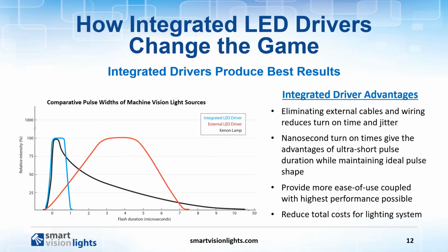Integrating the driver and controller in close physical proximity to each other on an LED motherboard eliminates the need for external wiring and ensures that high current pulses from the driver are delivered directly to the LED across comparatively short, impedance-controlled printed circuit board traces.